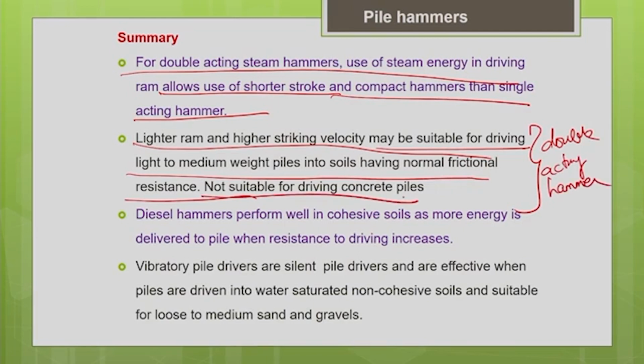It is not suitable for driving concrete piles. Generally for concrete piles, I need a heavier hammer so that I can reduce the height of fall, and also the blow rate of a double acting hammer is very high, which can easily shatter your concrete pile. For concrete piles, go for a very heavy hammer which can offer you more blow energy at a lesser height of fall.